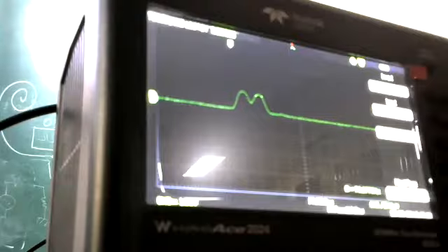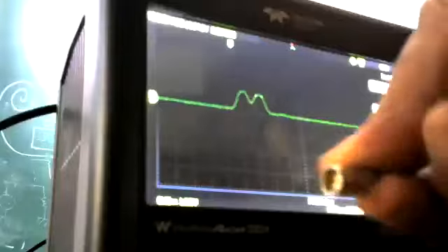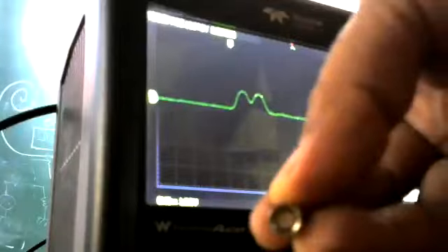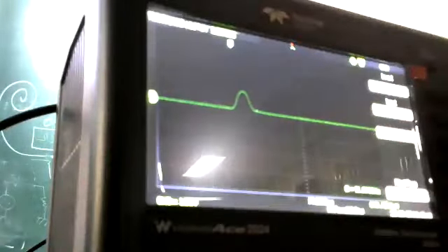And what I'm doing right now is, I have this little thing here, which is a 50 ohm load in the SMA format, so that I can just screw it on at the end. I'm now changing the boundary condition from being open to being matched. So the reflected wave is now gone. The one which travels all the way to the end is no longer coming back because it's hit a matched load. I take it out.